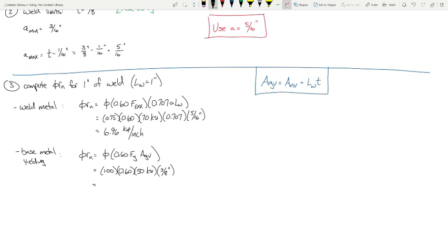Because if we're talking about, let's say, here's a plate, right? And we're yanking on it like this, right? Essentially the gross or net area is that area right there. I was talking about the phi value. Sorry. So the phi value just for base metal yielding is 1, right? That comes right from J4. It's page 16.1-137.